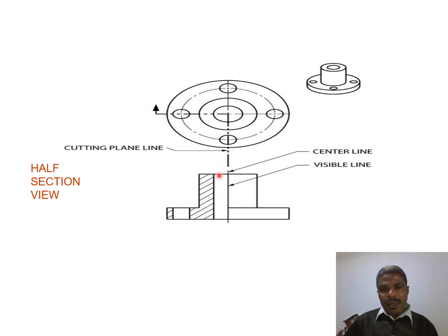Hatching lines, so you only work on this. Why? There is a repetition. This method is rather economical instead of shading again there, because this side resembles this one, so there is no need to continue doing the same thing. You simply indicate this part here, as you can see. We said this is also used for a symmetrical object. This is a symmetrical object.